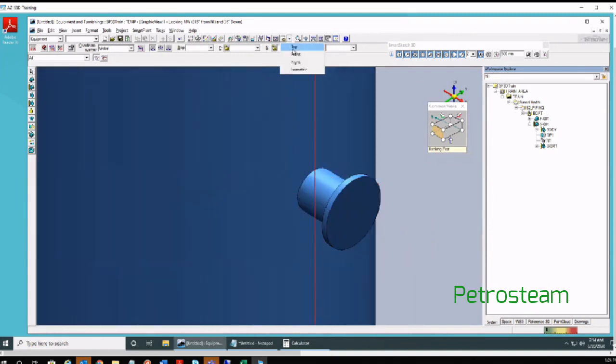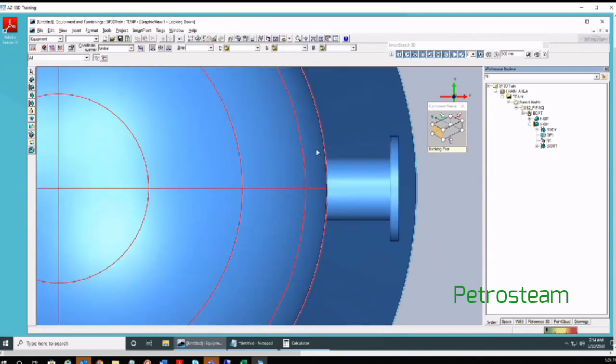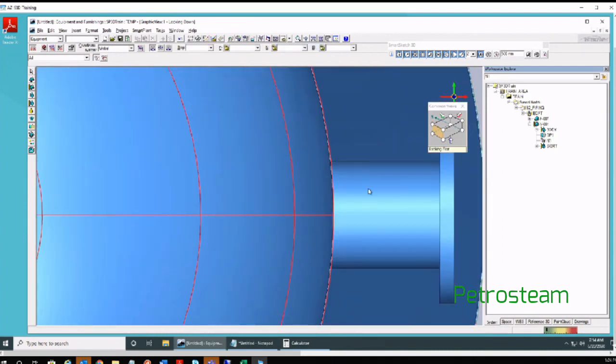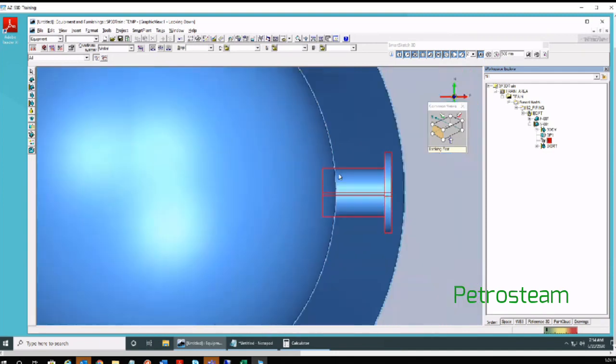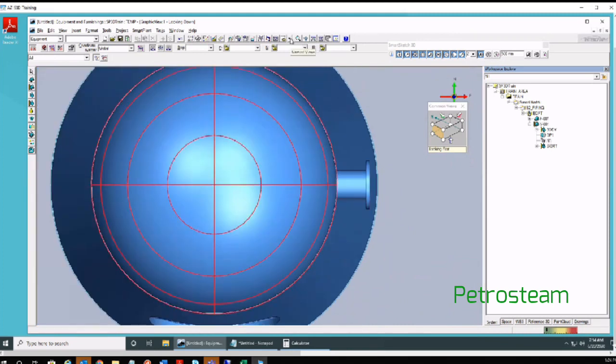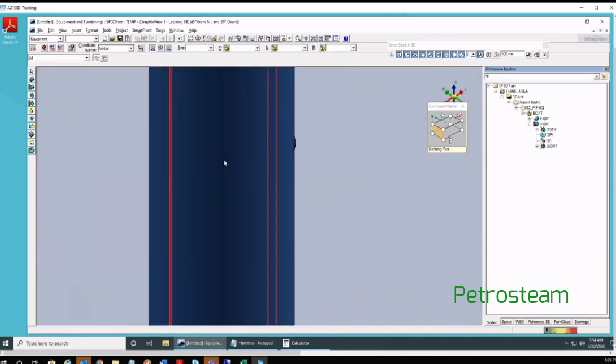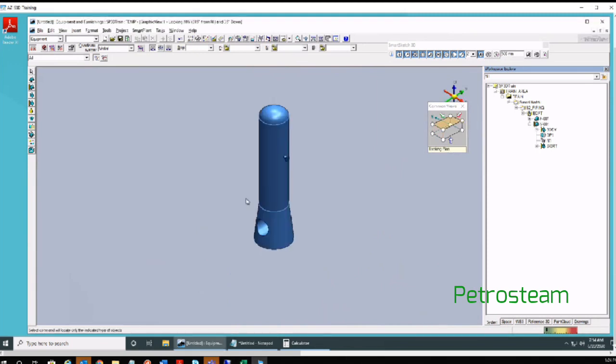In the top view also you can see this is your cylinder and the nozzle is up to here penetrating inside the cylinder. If I put exactly 200, maybe due to this curvature it will not penetrate through the equipment. This is how you will set your nozzle.